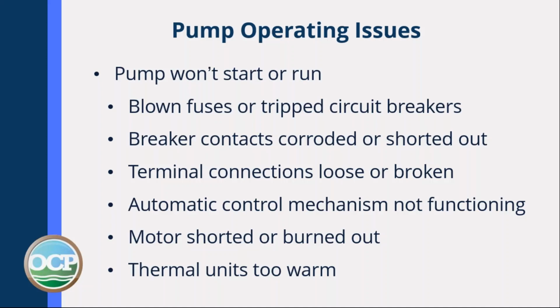If the pump's supposed to be set in automatic and somebody's got it set into the off position, it won't run. Check to see if the motor is shorted out or burnt out. Check to see if the thermal units are too warm to allow operation.